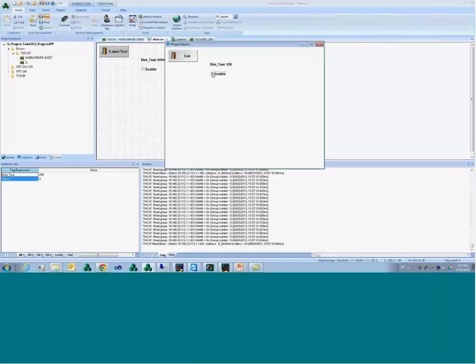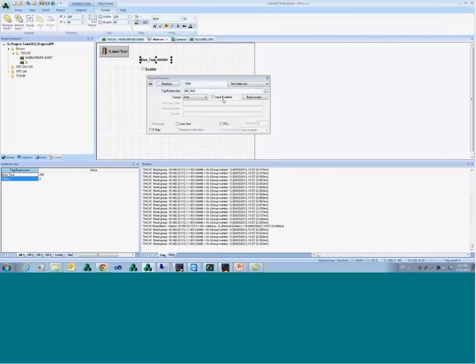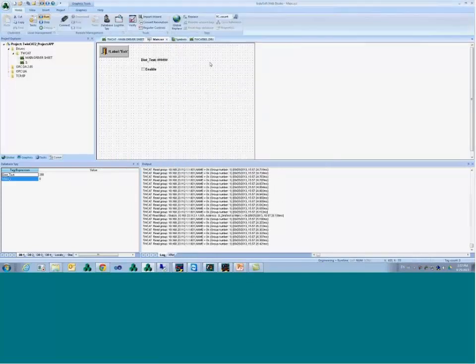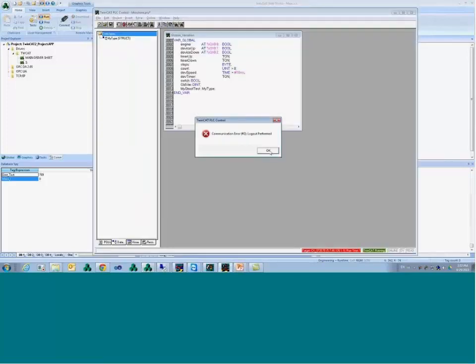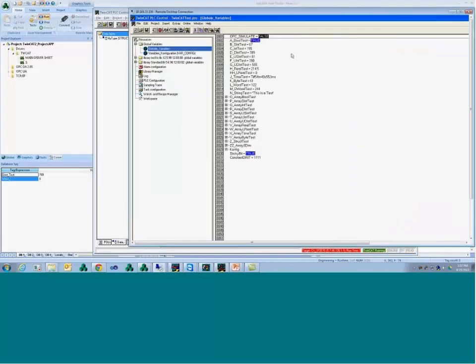So when I do this, I'm sending to the PLC the command to stop counting. So I'm going to enable here, inputs. I'm going to write to this tag, double int test. So I'm going to write here 789. When I look on TwinCAT, actually, it's going to be here, I have the value 789 that I have just written.